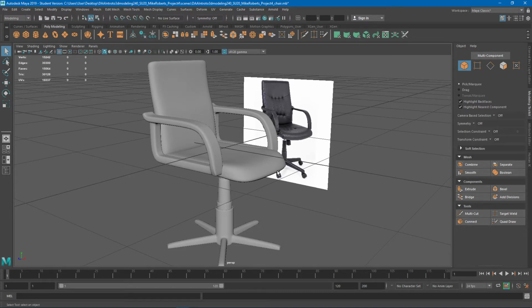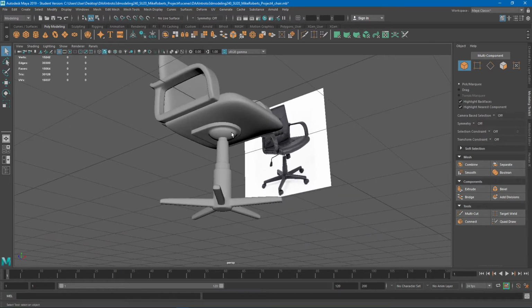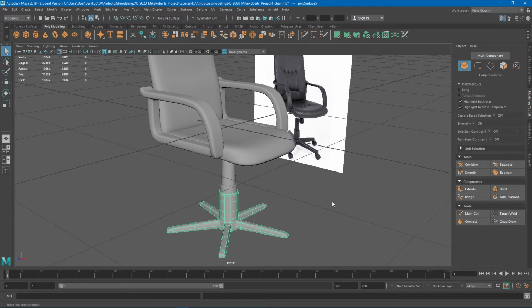Alright, so we left off having built a lot of the chair, right? We built a little underbrace, we built the spokes, we got to talk a lot about, if I hit W for move tool, how these move settings work, and how we can orient a component, or even edit pivot for custom, where you can numerically type in values, or even use snap features to give you some more localized control over the spokes, right? And that's one of the cool things about this part of the chair, it really lets us take a look at this.